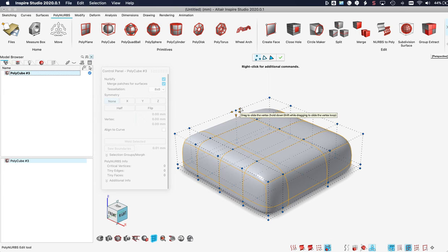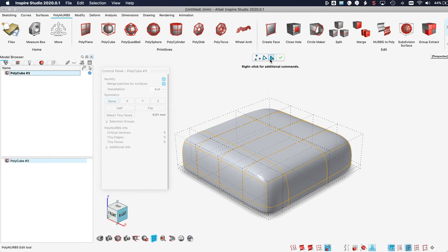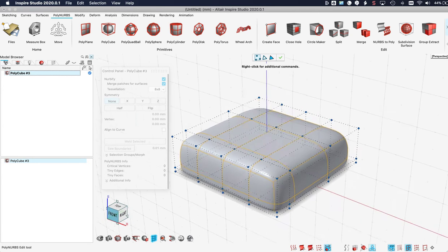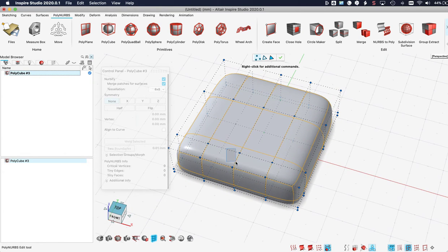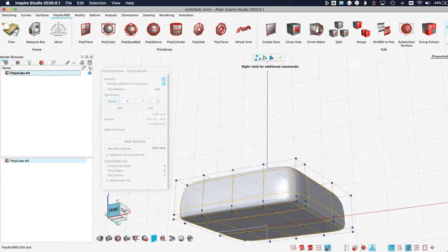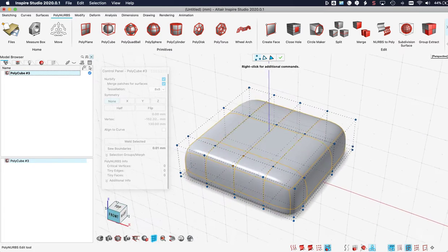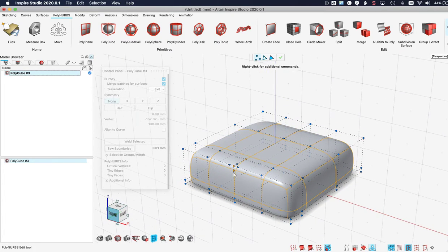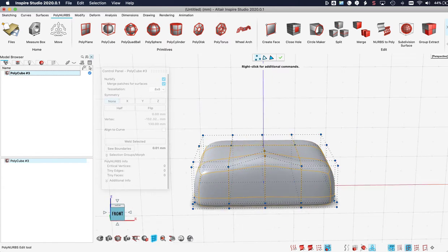So to edit this shape, I can choose between working with vertices at the top, or edges, or faces. Let's start with changing a little bit of the vertices, like these two in the middle front. I do a fence select, but I need to make sure I don't accidentally select points that are lying behind. So that is probably okay.